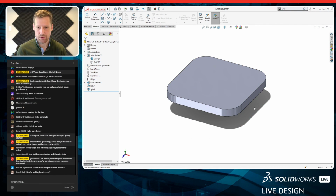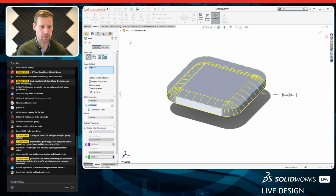Now, I'm going to focus on that real quick by hiding the bottom one. If I select this edge and choose fillet, I can go in here and I can say, okay, I want a symmetric fillet.